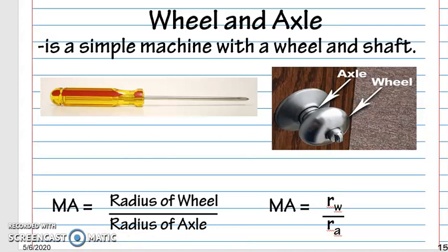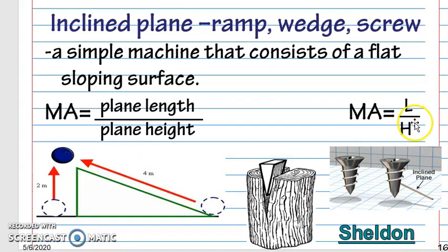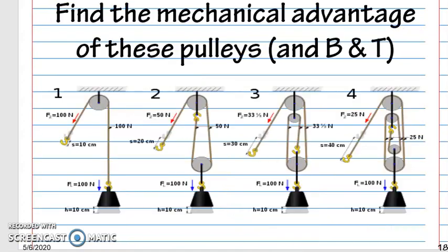Okay, inclined plane. You remember that formula. Okay, here's an inclined plane wrapped around a cylinder. Okay, and this one. Now, notice that, okay, I know that you know that the MA is already all written up here, 1, 2, 3, 4, but just look at this. Some people say, oh, there's one because it's got one pulley, but that's not true. It's talking about how much of the rope is separated from the mass. So right here it's separated in half from the mass. So it'll be twice as easy.